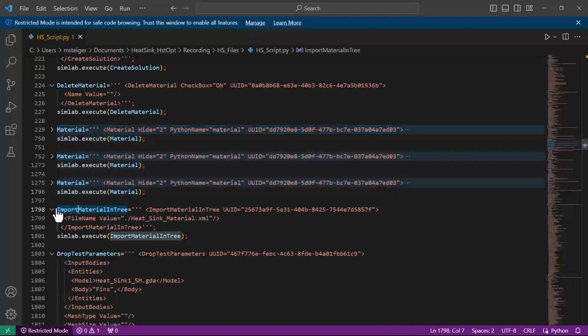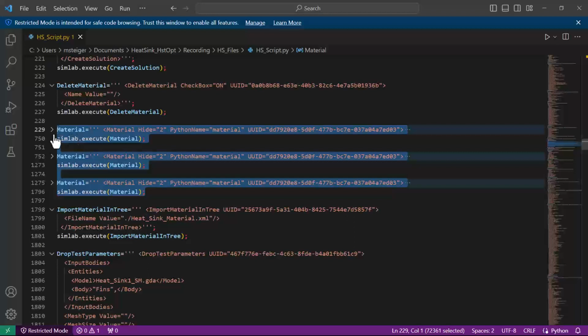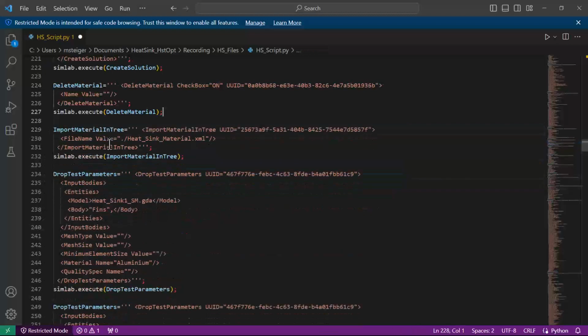But we also have our import material template function. Here we can decide whether we want to erase the import material template, which means we won't be using this .xml file anymore because our script will handle the creation of the material, or we can eliminate the material creation, which, as you can see, uses a ton of lines to define all the properties necessary, and just leave our template. This is what we'll do for this exercise. We are just going to erase the material creation.